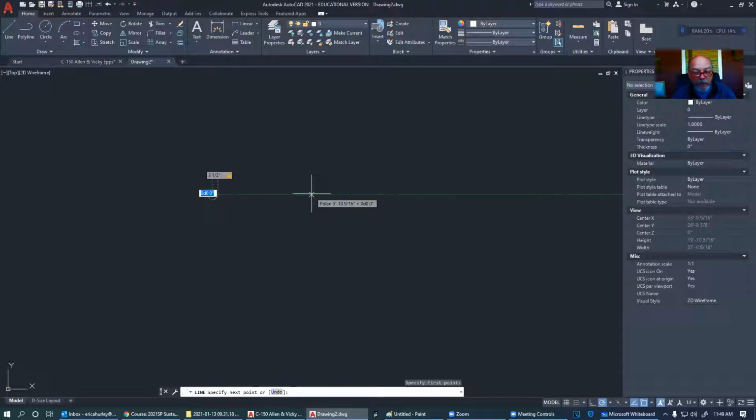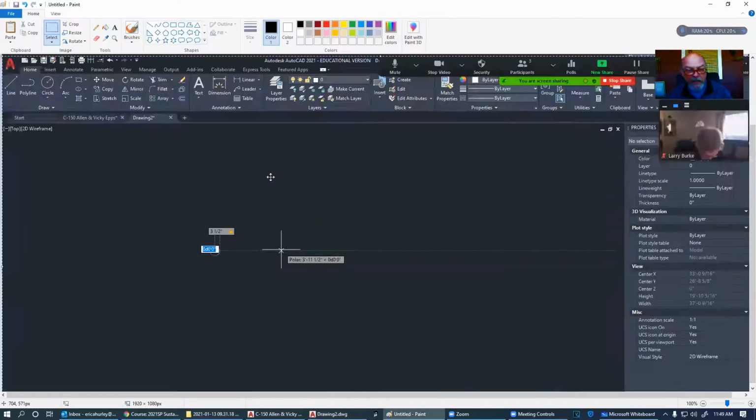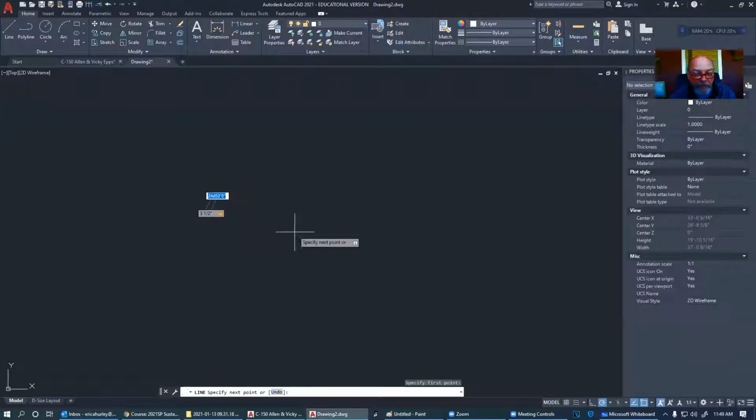So this is 0. And since I've already put 3.5 inches in, you'll notice that there's a padlock here. That means that this is locked in place. This is still open, but this is locked in place. And if I'm going in this general direction and it's showing 0 degrees, minutes, and seconds, all I've got to do is hit enter. Bam.